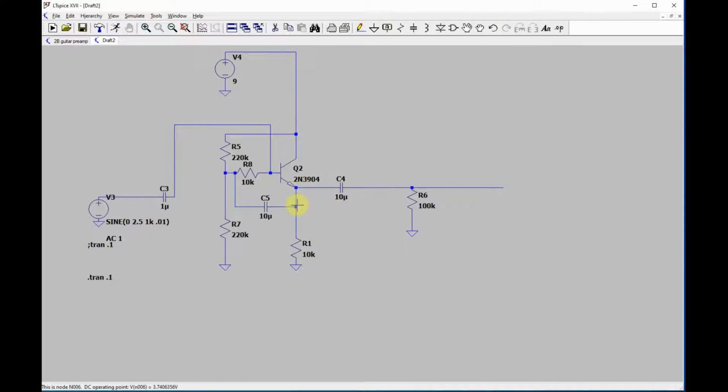What happens here is, technically, it's not negative feedback. It's positive feedback, but it's positive feedback that's less than 1. So your signal comes in here, comes out just a little less than 1, comes back and feeds itself into the base again. But the signal's coming in, and now it has to split this way, which is high impedance, like we already said. The impedance across here is going to be 3 megs or something like that.